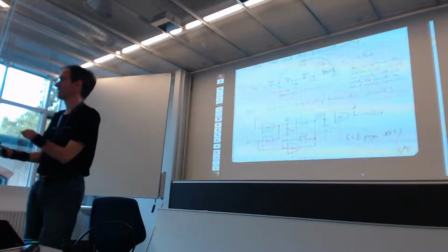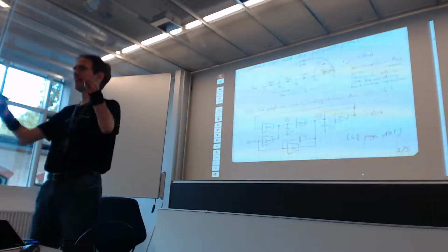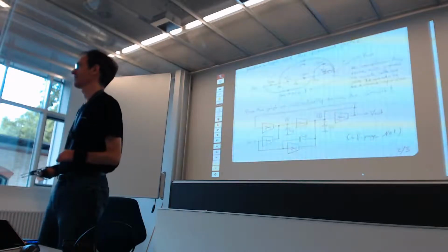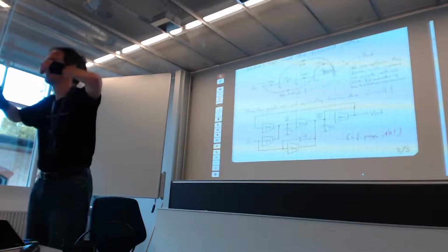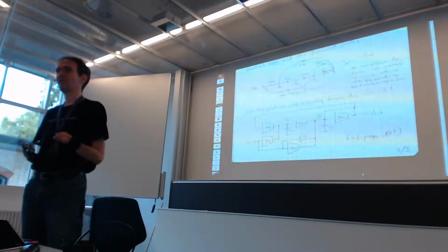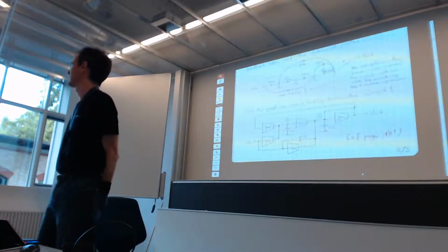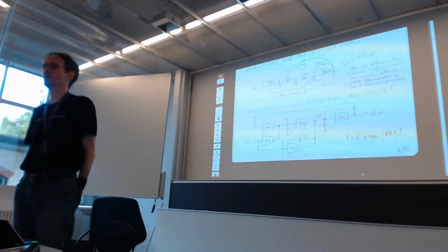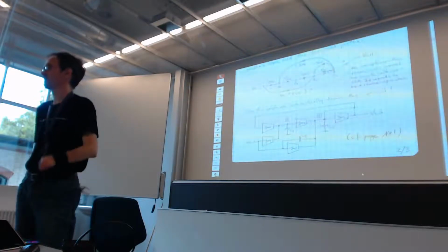Just by saying, this is my filter transfer function, I convert to integrators. I do the basic structure of the integrator filter, and then I reshuffle the paths until I see something which corresponds to a driving point signal flow graph that looks the same as my circuit would look. And then you have your filter.